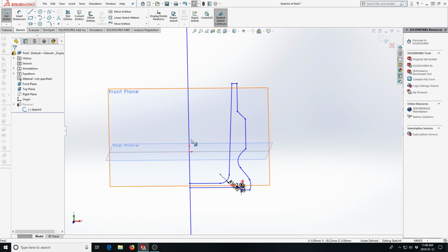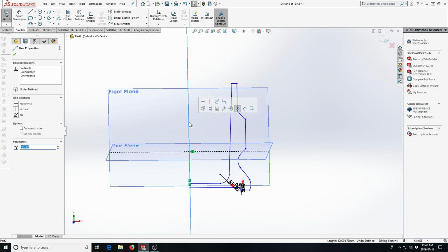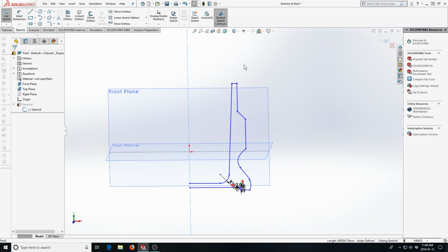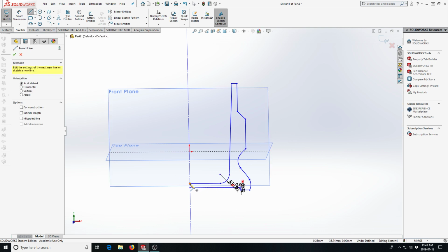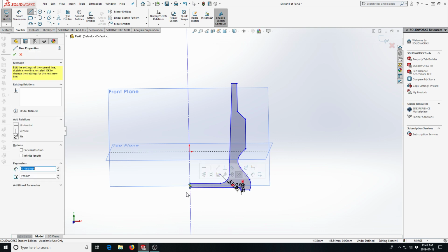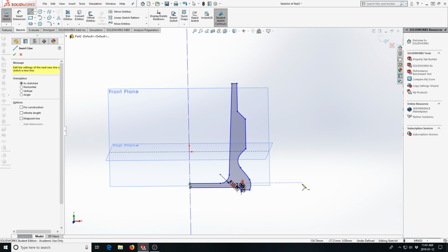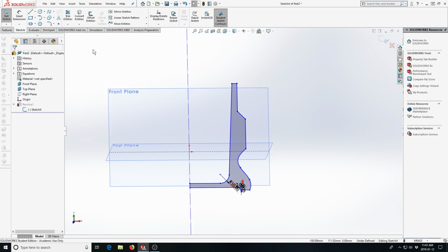And that should have been a construction line for construction. There we go. You can see you can make these construction lines, they'll be dashed, but they'll allow you to dimension things a bit easier. Now, unfortunately, what I've done in that is I've also opened up this cross-section, so I'll have to close it again, draw a line from there to there, and we're back to what we had, but now I've got this center line.